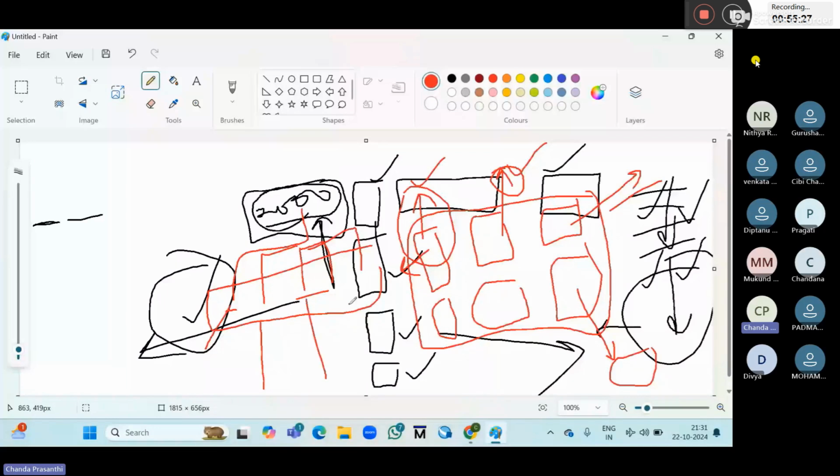Okay, so how do we write the coverage command? We mention the test name or suite name, configuration name, and test related things will be there inside the suite. In that we put all the things in the command. So we run the command. First we upload the coverage, then we extract the data. Extract the data in the sense of how many bins are hit, how many holes. So this is the total idea.